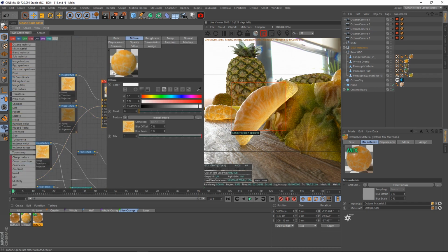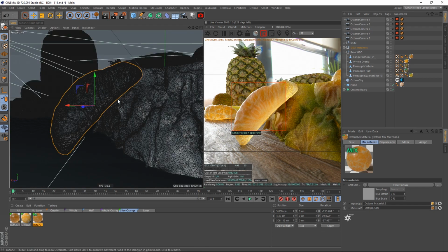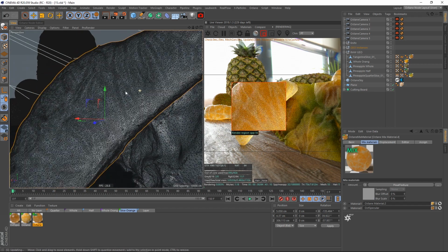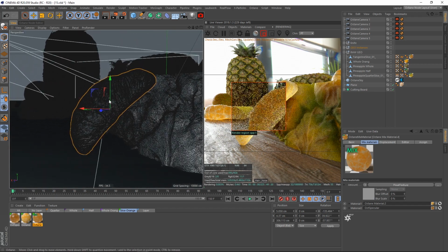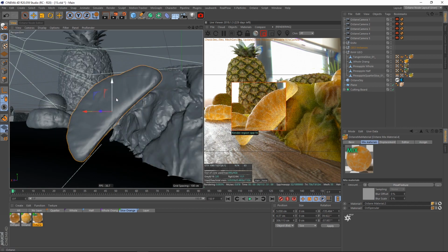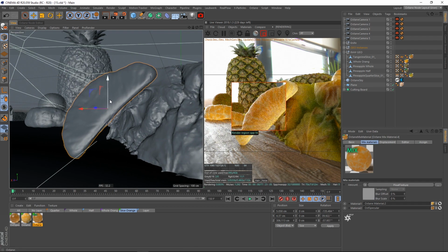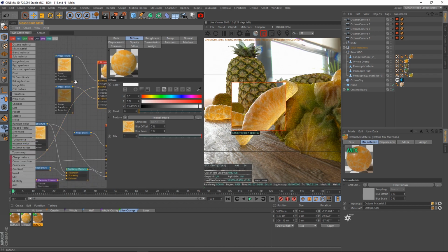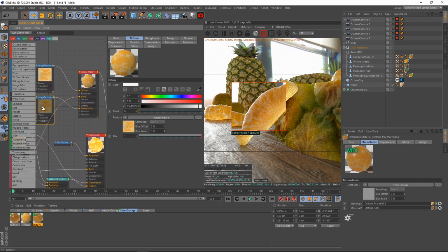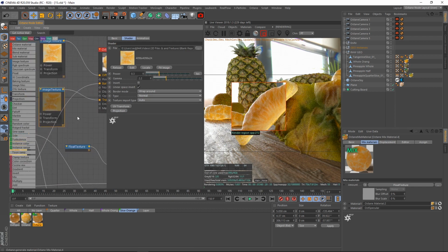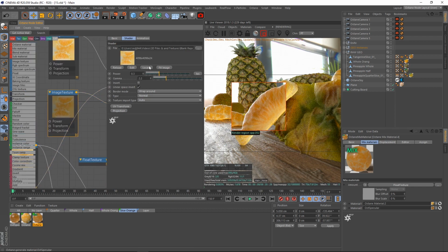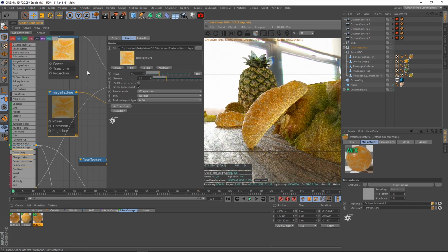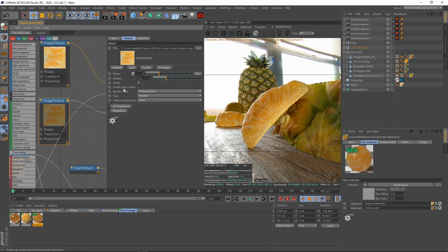All I did here, again, I just came with a raw mesh with a diffuse material, nothing special. So that is why I'm dealing with only that simple diffuse matte. Because we didn't have any fancy normal maps or bump maps, I had to make my own. So I took this image texture for the diffuse, copied it, and ran this into the transmission value. And I dropped it down because it was so darn bright, and a value of 1 just blew it out too much.